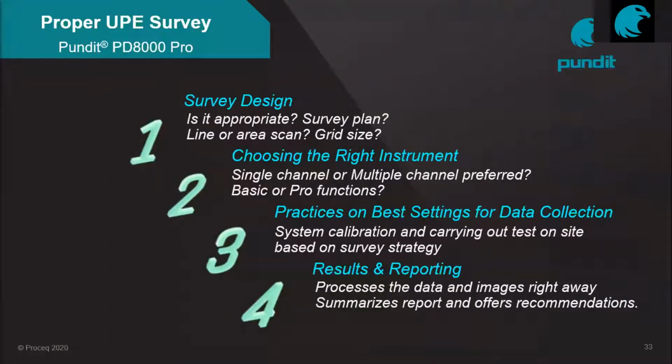First, we always touch on this kind of NDT survey or NDT testing. All these tests are first based on the site conditions and valuable information, for example drawings, and we can then set up our plan and design our survey. After that we can proceed to the next step, for example choosing the right instrument, maybe going for GPR first, followed by Pulse-Echo testing.